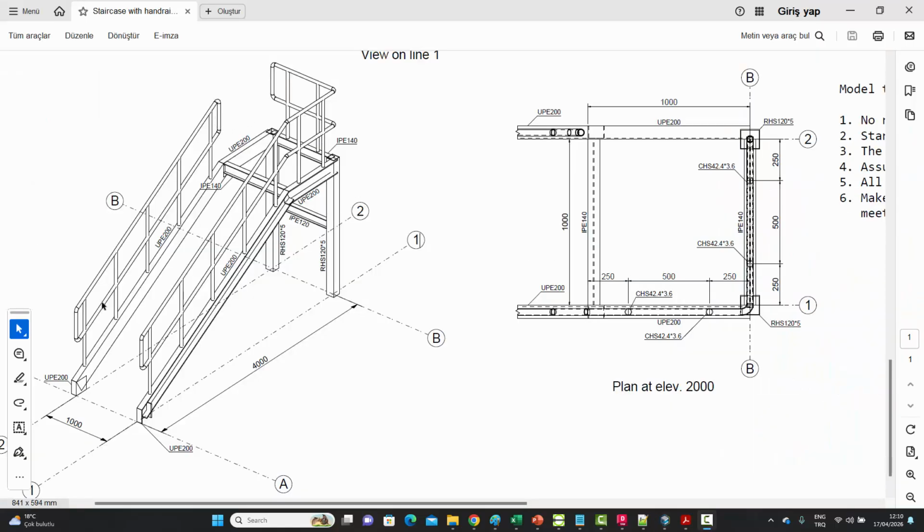Now what we've done is we've created this handrail. Don't worry about these little elbows at the corners. We'll try and do them at the end. But we've created this one, and we've got something very similar on this side. It's only that it's continuing like that, but it's mostly the same. So we can copy this whole thing to this side, and then do the modifications needed to do the rest of it. But we won't copy them because, if you remember, this has an offset of minus 40 in that direction. If I copy them like that, it might go in the other direction. A better strategy would be to select all these and just mirror them across the middle. In that case, the offsets would be correctly transferred.